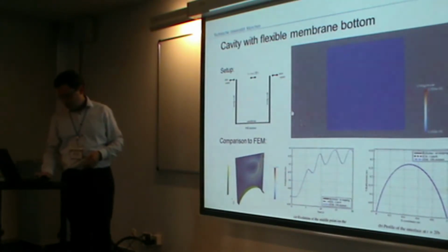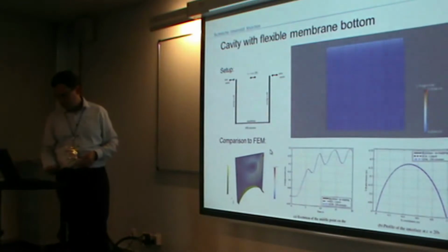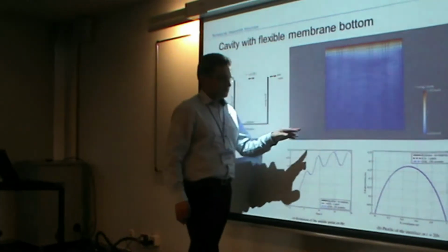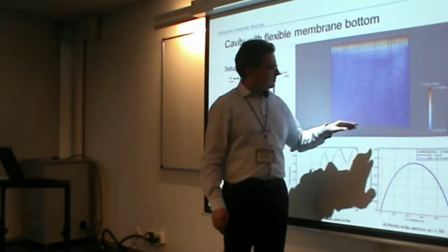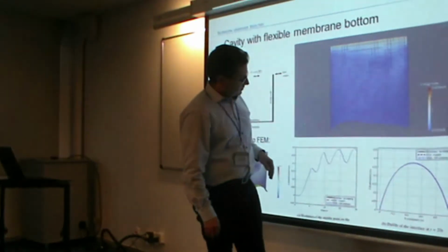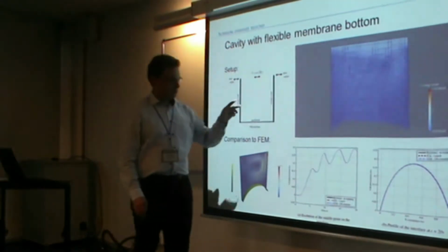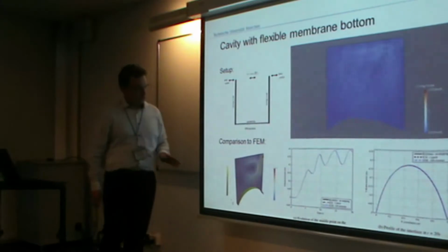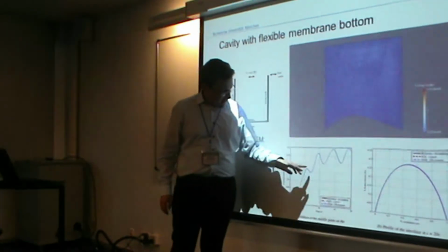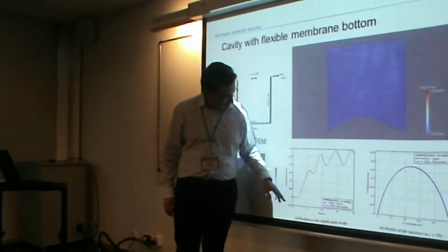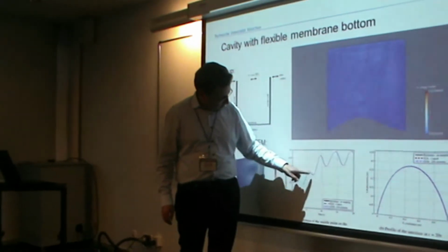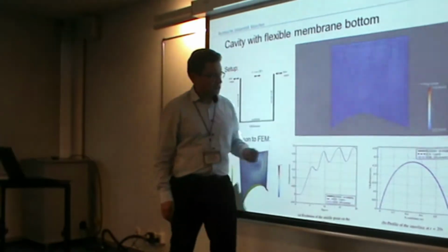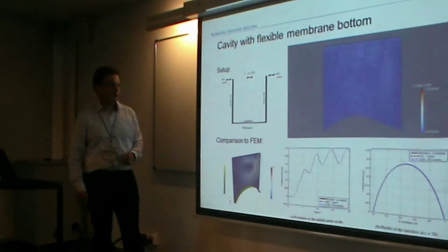So that's just the first test case. It's the classical driven cavity problem. That is, for example, with a membrane, which is put here, which is computed with our IGA solver. So it's just this moving top. Due to time reasons, I think we don't wait until this is going up. I don't know why it's going so slow here. At least what is important, we have a reference solution with an overkill resolution. We have an IGA solution, and we have standard FEM of this year with the non-matching grid mapper, which we also have working in our environment.